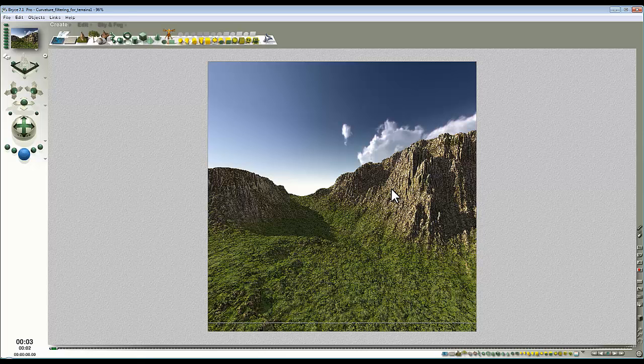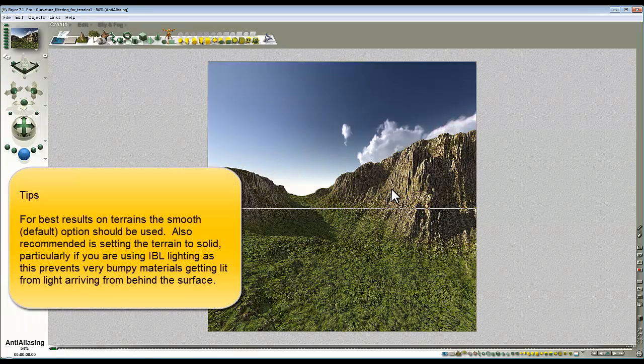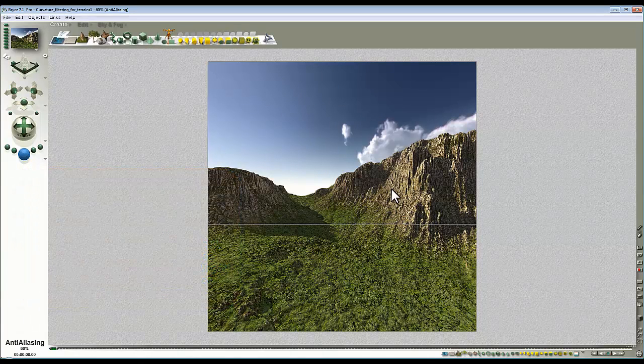Curvature is highly dependent on the geometry of whatever you're applying the curvature filter to. If the resolution is too low, it can only detect curvature across individual facets of the mesh. The lower the geometry of the mesh, the harsher the transitions will be in the curvature filter, and you might see some pixelation occurring, but it's not pixels on the screen, it's pixels that are actually facets of the mesh that you're seeing as the curvature is trying to determine whether that particular facet is concave or convex. So high resolution meshes are essential, as is a lot of patience.